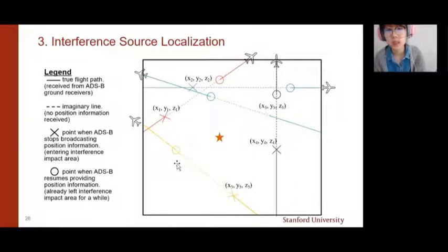Why? Because when the airplane loses the GNSS signals, it needs some time to do acquisition and tracking before it can recalculate its position information and rebroadcast the ADS-B reports. Because of the complicated nature of that procedure, we decided to just use the starting point of the gap, which we assume is theoretically on the boundary of the impact sphere.